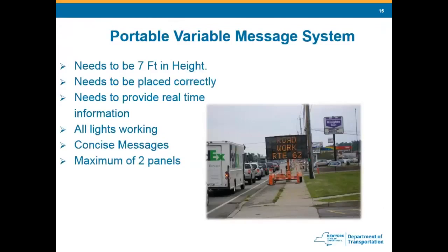Now on this one, I don't know where this was taken. You see it's in the middle of the sidewalk. I can't comment on that, only to say that there may be no other place to put it. That's not ideal, but there may be no other place to put it. If it does end up in the middle of the sidewalk, we need to keep in mind that we need to direct pedestrian traffic. We need to have a detour for the pedestrians noted because of that.